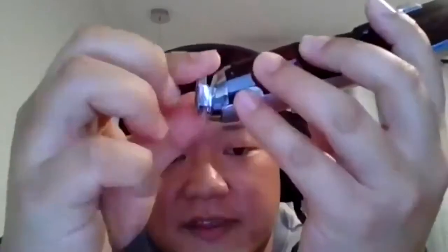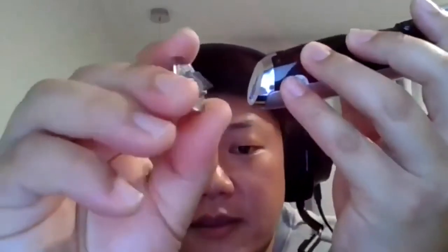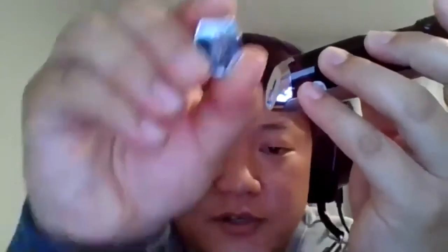And then you want to use your little cleave tool, which is found at the bottom of the unit behind the battery cover. I'll just find that for you. So it comes off at the back here, you lift that up. You're not actually going to use this little sharp tool to just hack away at the fiber optic. You want to put it on a nice flat surface and make a nice straight line. Then you grab it with 2 hands, grab the shorter end where you're going to cleave it off, and the other hand, and you just literally snap it like a sprig of pasta, I guess is the best way to describe it.